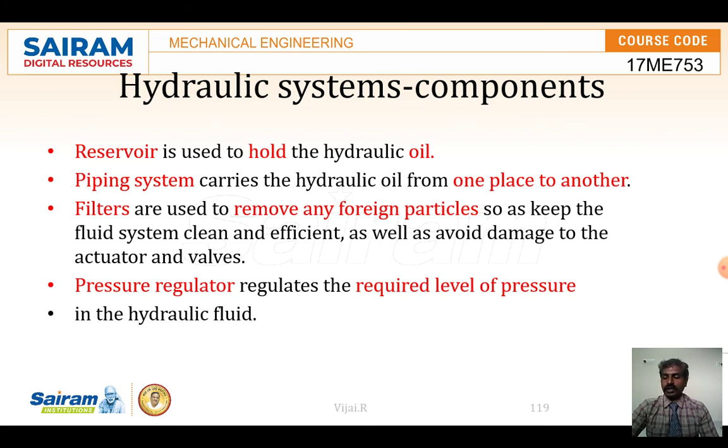Otherwise, if any foreign particles are present and go to the pump system or the actuator system, they can affect the performance of the system. The wear and tear will be more, and it may cause damage to the actuators and valves, so that should be avoided in the beginning itself.